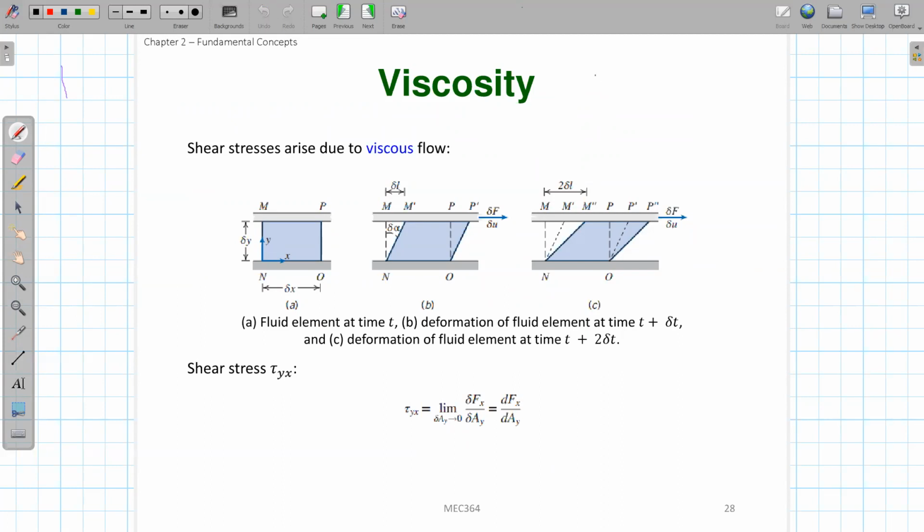And later on, we will know that the normal stress is the force working normally on the fluid part. So it's just equal to pressure. Why? Because we know that the fluid pressure works in the normal direction, not in the shear direction. Also, pressure is defined as force per unit area, because the pressure unit is Pascal, which is equal to Newton per meter square. So the pressure is a kind of stress in the normal direction on the surface. You can just think that the normal stress is just pressure.